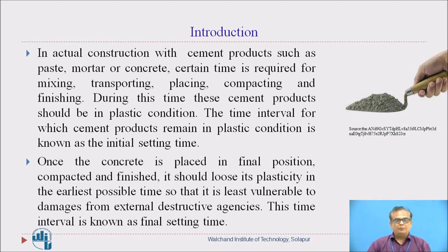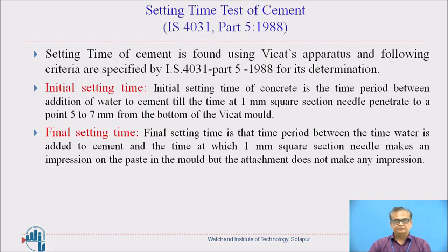Then what is final setting time? Once the concrete is placed in final position, compacted and finished, then it should lose its plasticity, and this should become possible at the earliest possible time, which will lead to least vulnerability of this particular concrete or product to external destructive agencies. So this time interval is known as final setting time of cement.